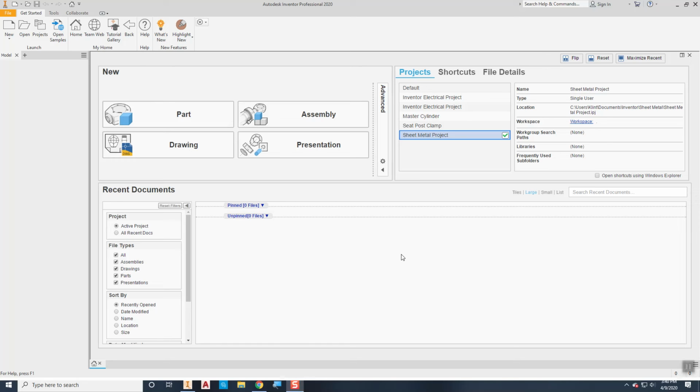Okay, this video is going to demonstrate how to use Autodesk Inventor to create an iPart. iParts are commonly used in Inventor because you can take one common design and modify it so that you can get several parts that maybe have a common theme or a common design and nest them all into one part rather than having several different parts. They can all be one with one basic design.